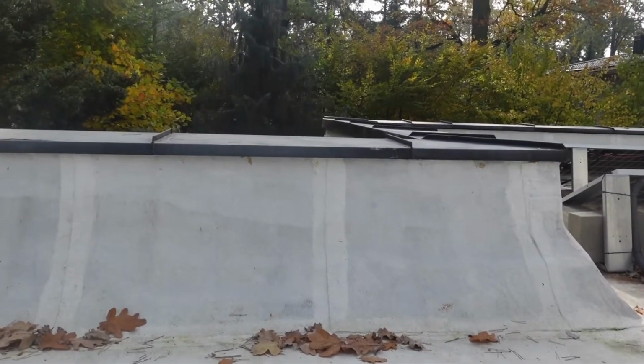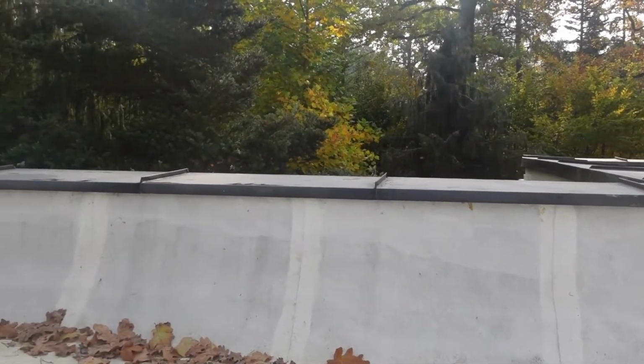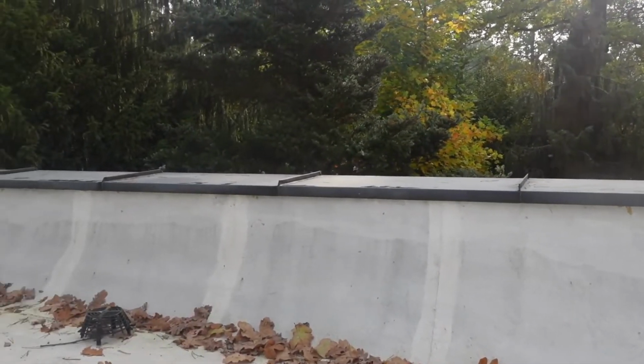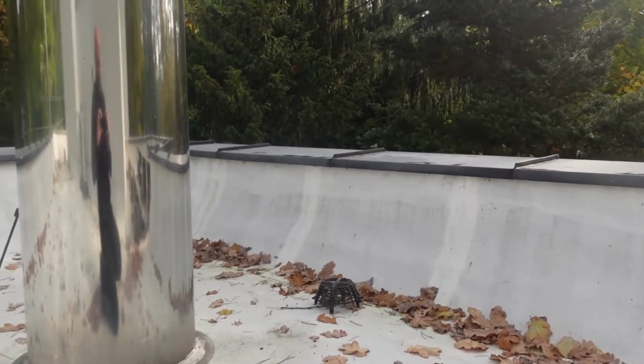You know, the water seeped through the ceiling into the building and resulted in significant water damage, you could say on the entire surface of the house. The roofing felt detached from these parapets. So it's no wonder the building's deterioration progressed. You can imagine it stood unused. Winter came and everything started expanding due to the frost, so the damage worsened.